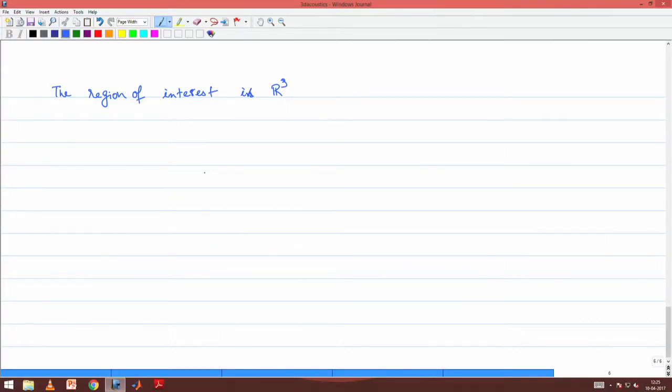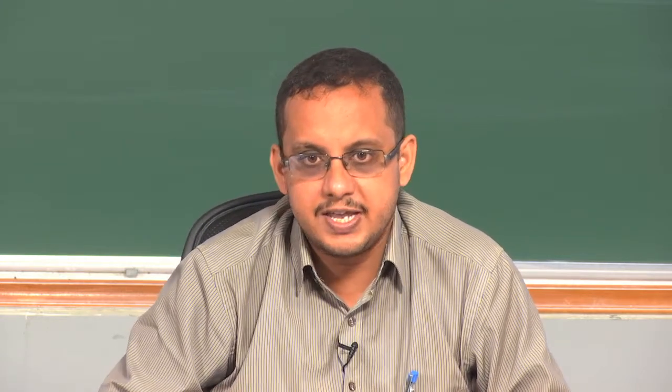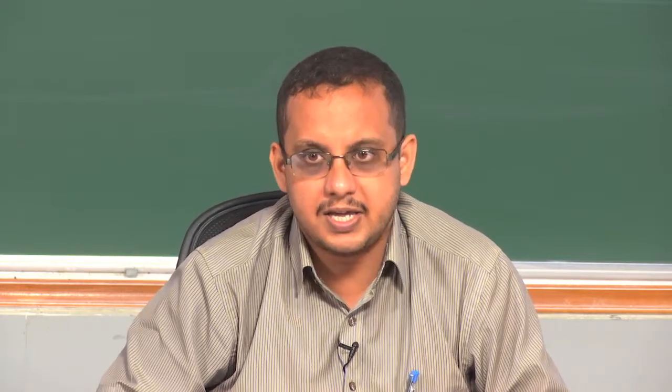But now let us say that we are worried about this entire 3 dimensional world, and in this 3 dimensional world there is a pulsating sphere, a sphere which just pulsates radially inwards and outwards, right. So, now can we say that the volume is really conserved? No, because the mass in turn is not conserved, because now this sphere is pumping in the mass and also sucking in the mass at alternate time cycles, right. So, we would like to include the effect of such inhomogeneities and again rederive from those very first principles by including these effects of non-homogeneities.